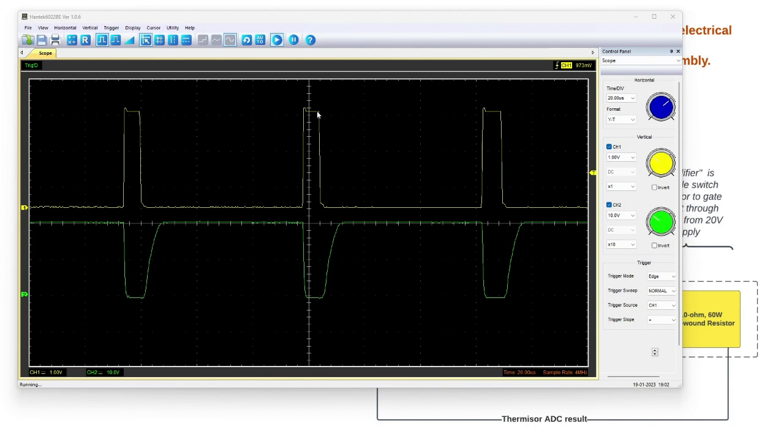When this pulse goes high, our pulse width modulated output, that switching transistor closes the low side of the resistor to ground, and suddenly current rushes through the resistor. The voltage on the low side of the resistor is now just about at ground, subject to the transistor characteristics. The transistor sits between the low side of the resistor and ground, but we ignore that. We'll treat it as a perfect switch. And what's happening when this green signal is low is we are dumping current into that resistor. This is the heating period, if you will. And we're at steady state.